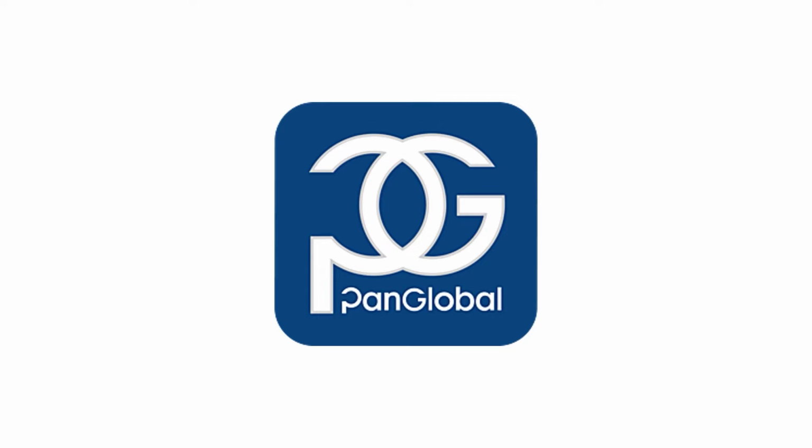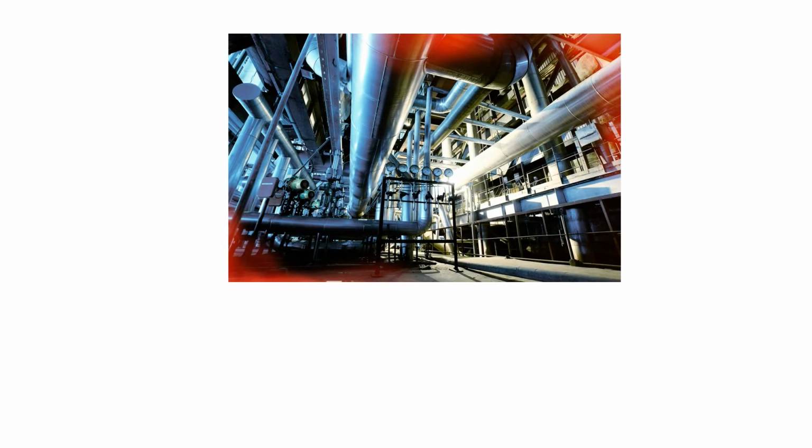This week, we are looking at an example of linear expansion of a pipe. Almost all solids expand when undergoing a temperature increase. If the process fluid in a pipe has its temperature increased, the steel pipe will expand in the radial and linear directions. The linear expansion of a pipe must be accounted for in the piping design phase of an engineering project. Components such as pipe supports or pipe hangers with springs are used to allow for pipe movement. Expansion loops in long runs of pipes are also used.